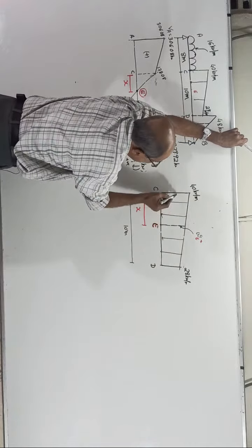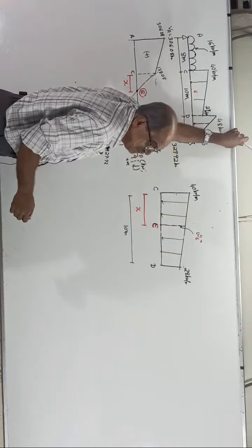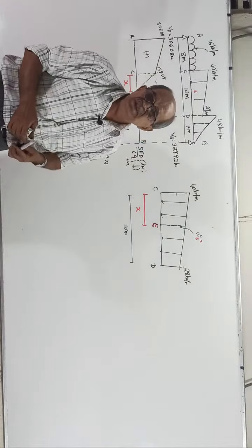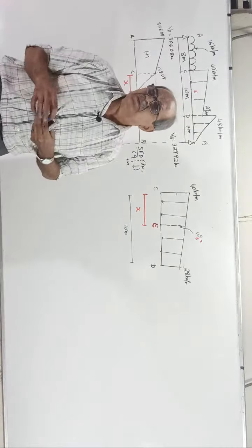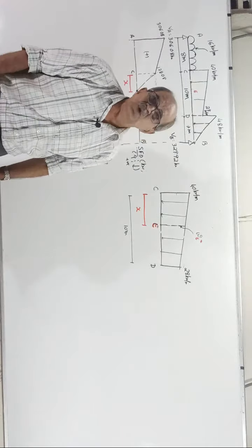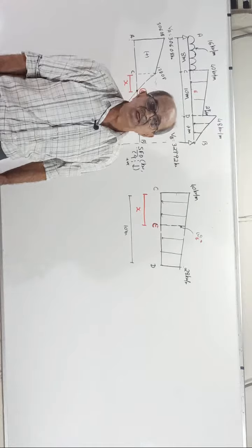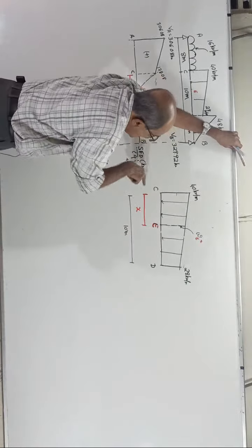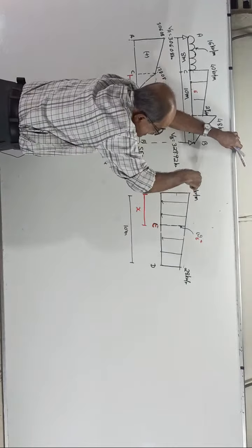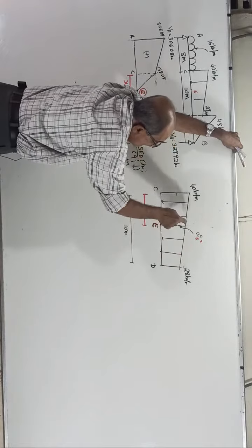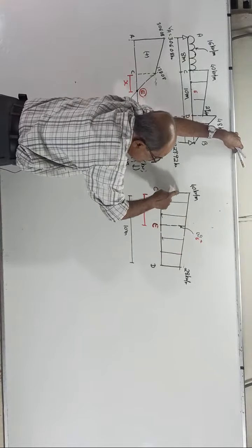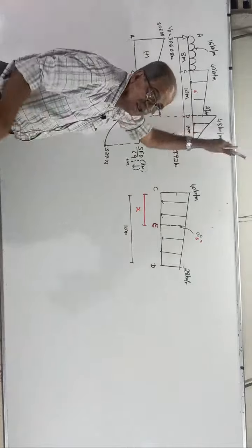Sometimes people will put a line here and apply something. Don't do it. You are engineers. Linear interpolation, if that is not known, not fit to be a structural engineer. Therefore, I am taking X from here. From 40, it will reduce to 28 there. How much will it be here? It is less than 40, more than 28.